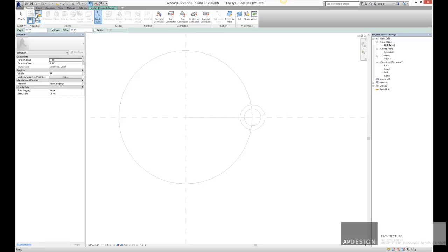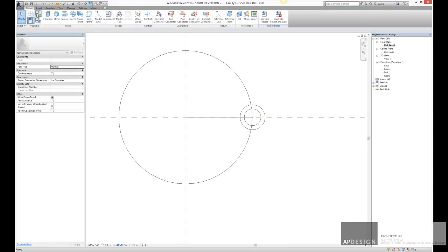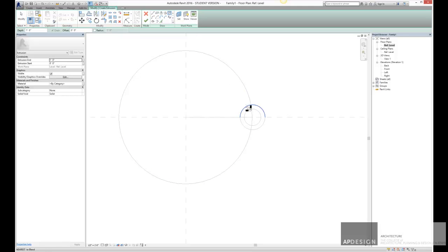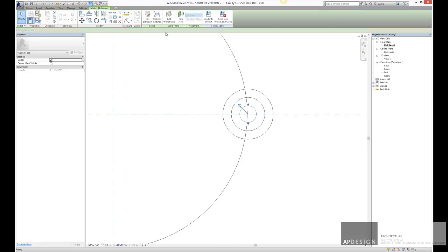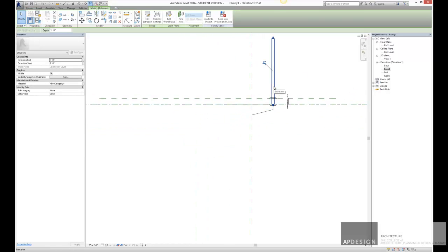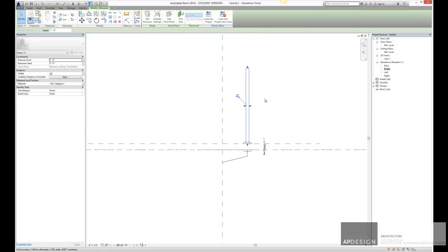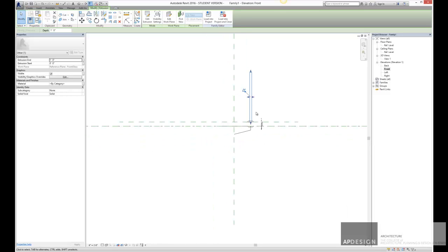So I'm going to use extrude. Just to show you again, I'll create an extrusion, create a circle, and this one will be 1/4 inch radius, and we'll say OK. We'll go to the front view again, and what we want is to have this begin at the front of glass, and we're going to add in a little more intelligence. When you use parameters, you can set up formulas so that it goes exactly an amount.